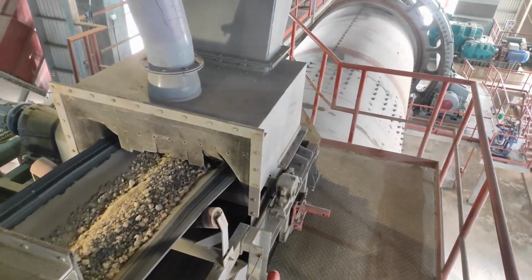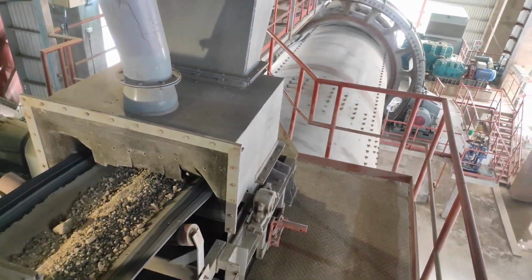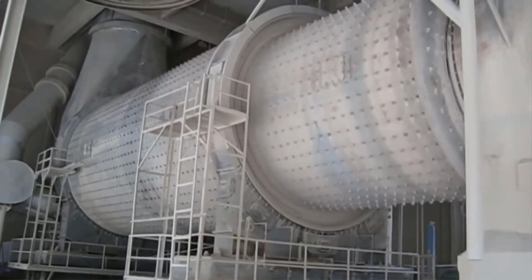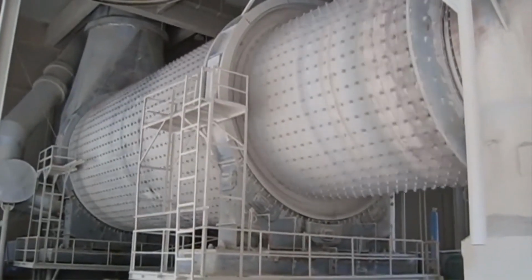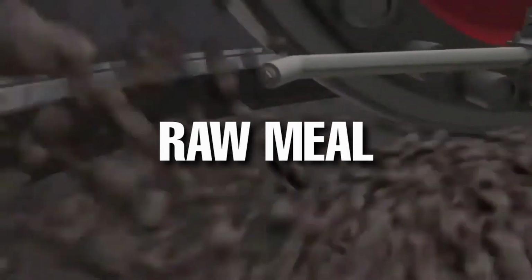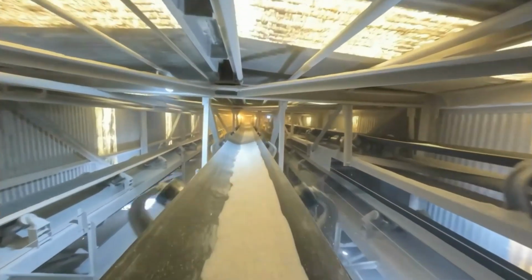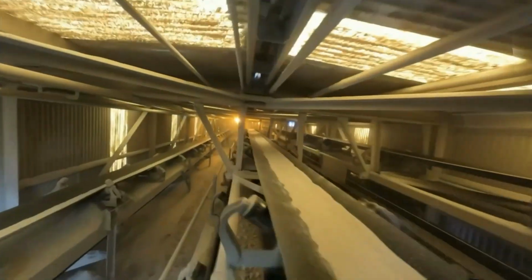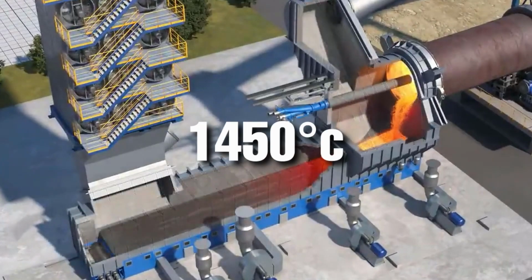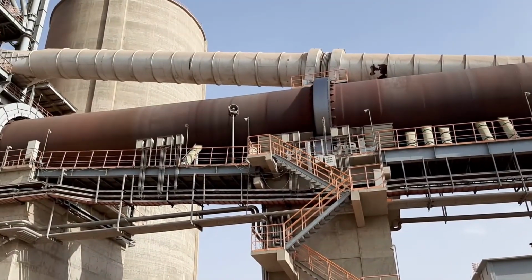The powdered limestone, clay, and other raw materials such as shale and sand are combined in precise proportions and blended. This process ensures that the ingredients are thoroughly mixed and homogenized, creating what is known as raw meal. The raw meal, which is a finely ground mixture of raw materials, is then heated to extreme temperatures, reaching around 1450 degrees Celsius in a rotating kiln.